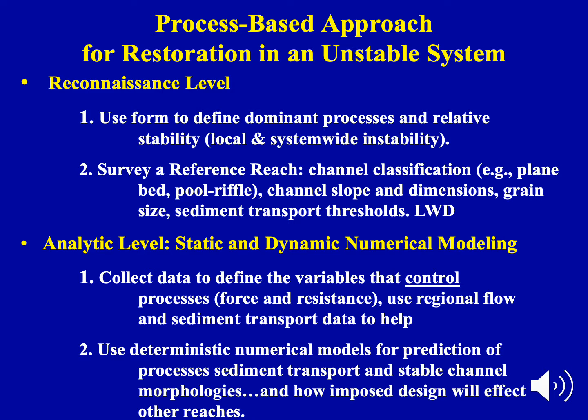Then down here, Rick is going to really cover modeling in his talk, but you need to actively look at what your sediment transport capacity is. What are the stages of your bankfull discharge, your Q10, and even higher flows. So modeling needs to be a component of it.